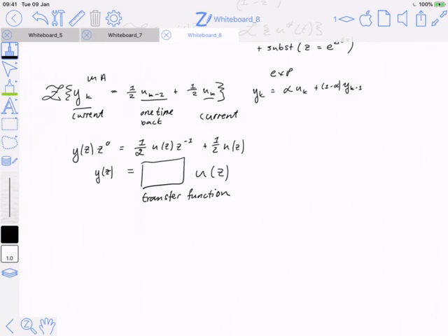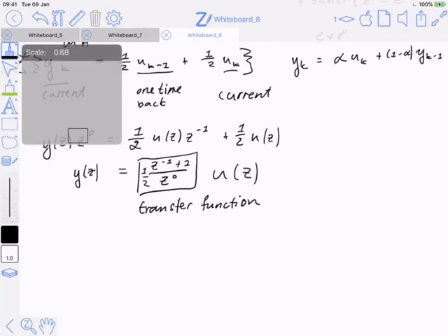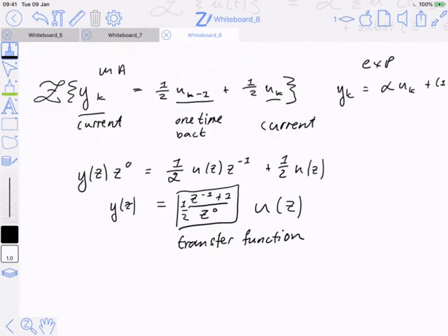And now, at this point, once I've done the Z transform and seen how the shifts work out, I can easily just solve, right? If this was a very complicated thing, I would use SymPy to do the solution part for me. If it's something like this, you can kind of do it by inspection. So that's effectively now the transfer function. We have now just basically discovered the transfer function of a 2-element moving average.